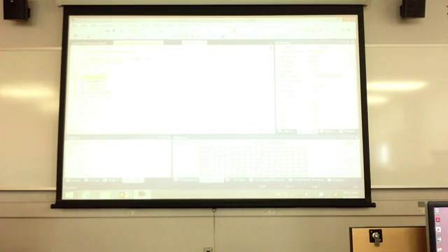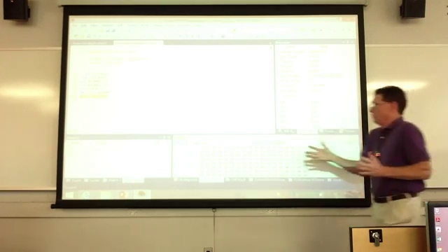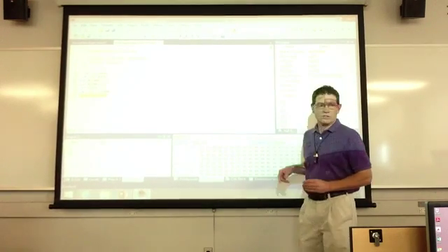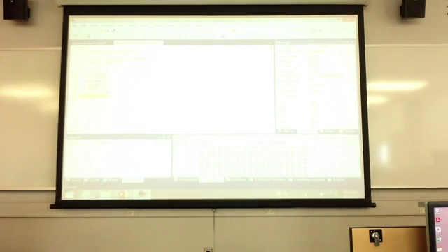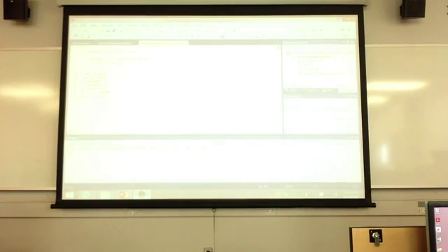So we run this down, and then we're just going to go look. Again, we can jump around in here. All we did was write those two numbers in there, and there they're sitting at 1,000. Now let me stop this process. Instead of 1,000, we're going to put in 100, and this is going to answer your question, sir. When we build this, now we change, let's go down to IRAM, and we're now going to physically change this to, instead of 1,000, 0100.